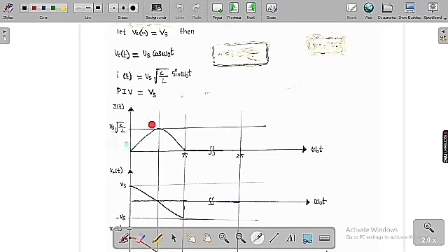So finally the maximum value is Vs into under root of C by L. After that the current is 0, because current being negative means the diode is going to turn off. Now the inductor voltage is equal to the capacitor voltage. If you substitute omega naught t equal to 0, we are going to get Vs, and if you substitute omega naught t equal to pi by 2, we are going to get 0, and if you substitute omega naught t equal to pi, we are going to get minus Vs. So this is the graph we are going to get for the inductor. But when current is equal to 0,